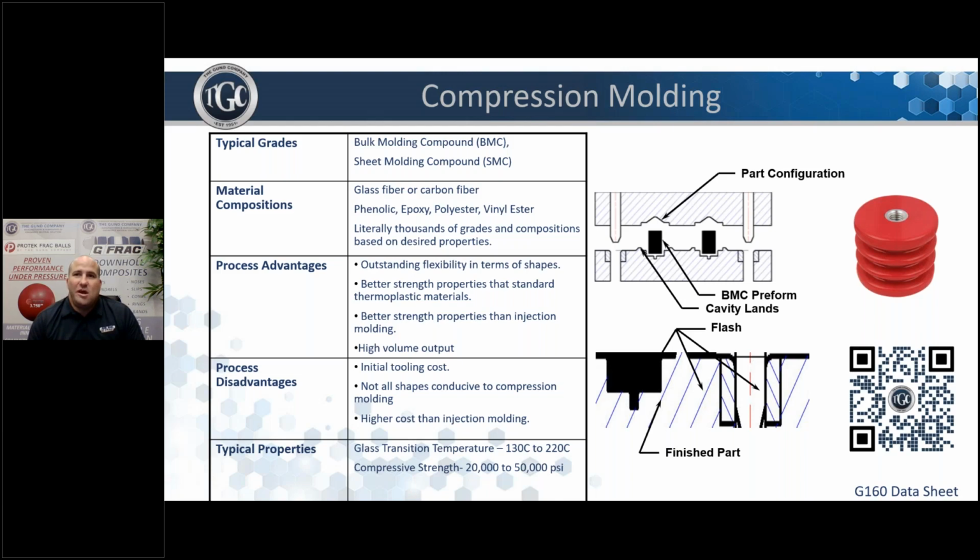With setup fees and run times, it can increase your part costs on smaller volumes. There can be limitations on part sizes. It would be hard to find a press and mold to produce larger parts you see in most casing tool sizes, say up to 13 3/8 inches up to 24 inches, but they are out there. And compression molding obviously works great on smaller parts.